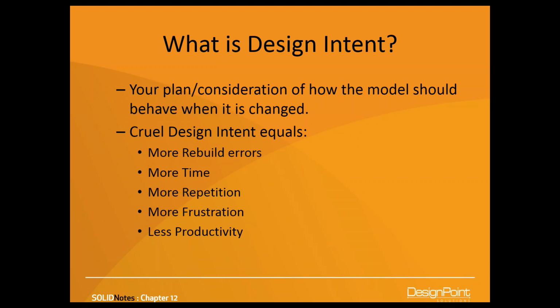So you're constantly creating revisions, and because of that, we want to make sure that with good design intent practices, we can make those revisions as simple and as easy as possible without taking that much time. If you're spending more time remodeling the part than when you initially modeled the part, that's showing some bad design intent practices.